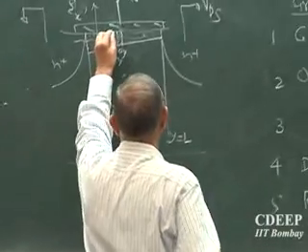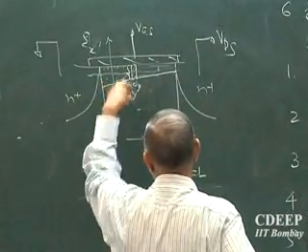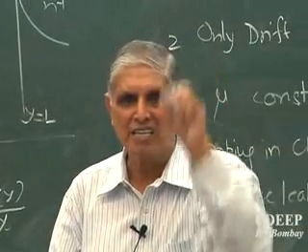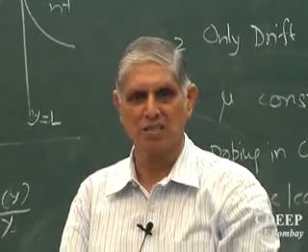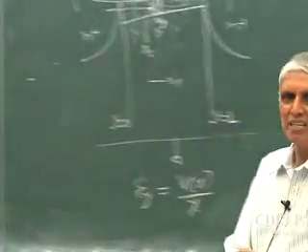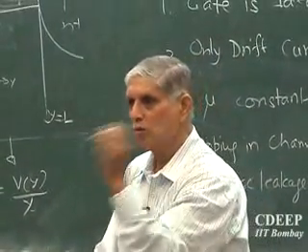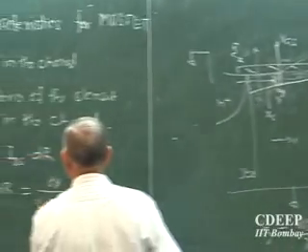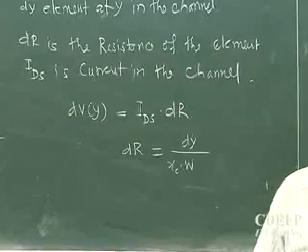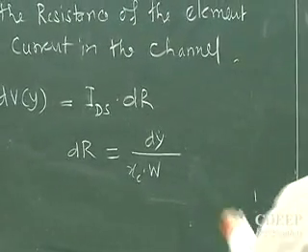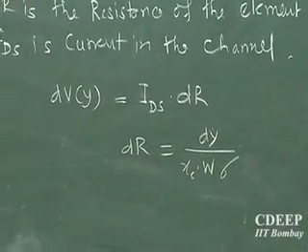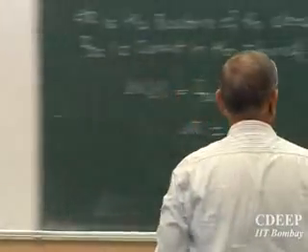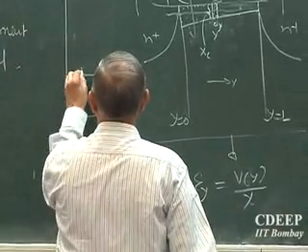The width of this channel, or what we call the thickness of this channel at this point, is called xc. So along x direction at that dy point, let's say x is the channel length. Is that correct? So what is the area then for this element? Xc into W, because this W will be appearing. So area is Xc into W, is that clear? Into sigma, because sigma is the conductivity. Now this sigma is slightly varying. The reason is, as we have just said, n is varying along this. So there is a profile in this element which you are looking at, Nx.